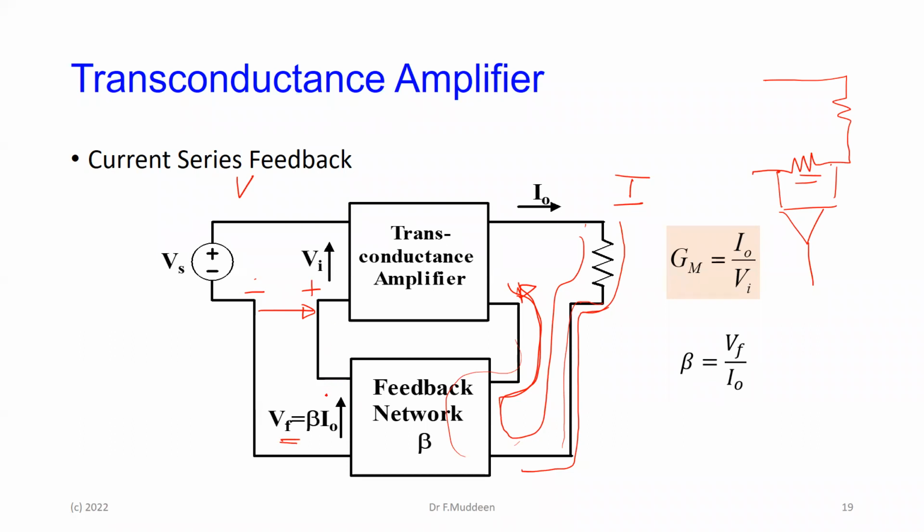Series, because it's a voltage coming out, it has to go in series with the input and of course provide negative feedback. So again, Vs is equal to Vf plus Vin, or Vin is equal to Vs minus Vf, your negative feedback.